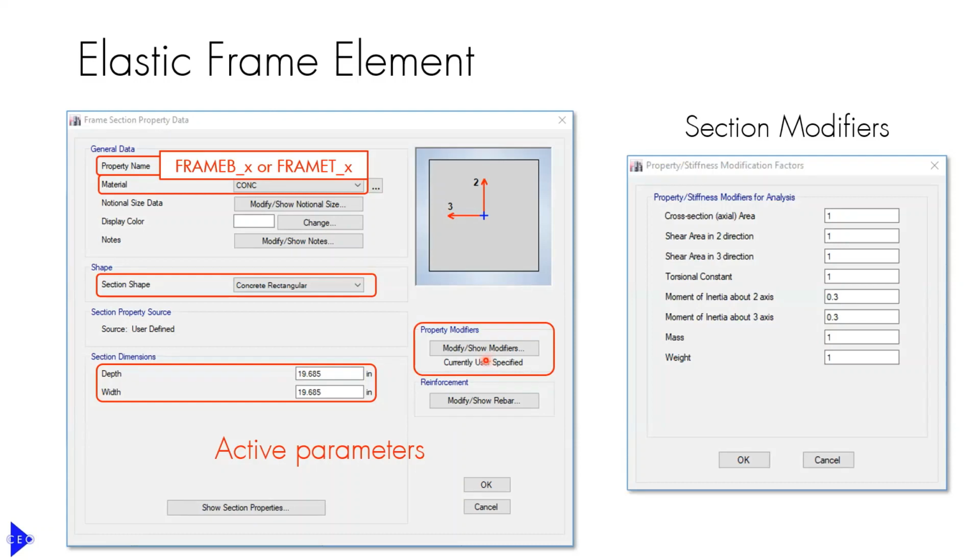And then that automatically converts into an OpenSees elastic, either Bernoulli or Timoshenko beam, with the moment of inertia, area, modulus of elasticity, and everything that's assigned in ETABS already. So that's also automated. The software connects the material with the sectional properties and writes that one line of command in OpenSees.